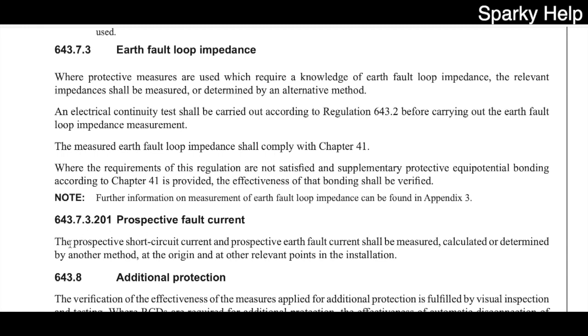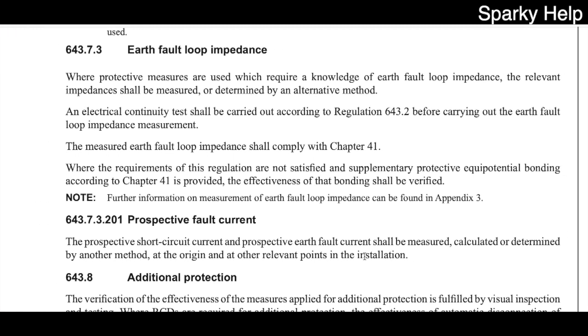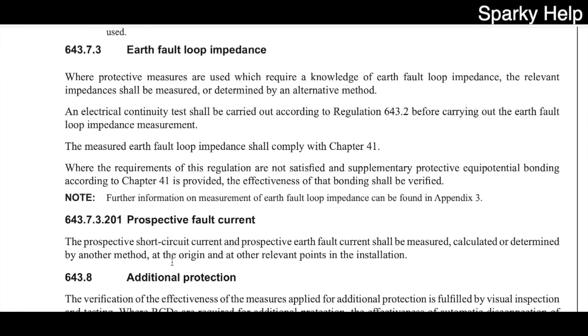Prospective fault current then, the prospective short circuit current and prospective earth fault current, so that's the PSC and PFC, shall be measured, calculated or determined by another method at the origin and other relevant points in the installation, and therefore that ties up with the other regulations that we just looked at relating to protective devices, and that is that they should be able to withstand whichever is the higher of the fault currents at the locations at which